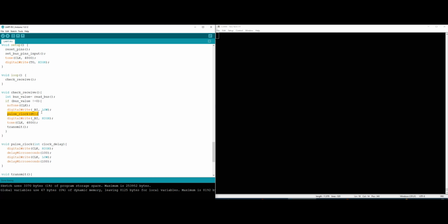Doing so results in the data on the bus being read into our B register. So I'm stopping the main clock on the computer, reading that value, and pausing the clock, which means we're saving that value into the B register.